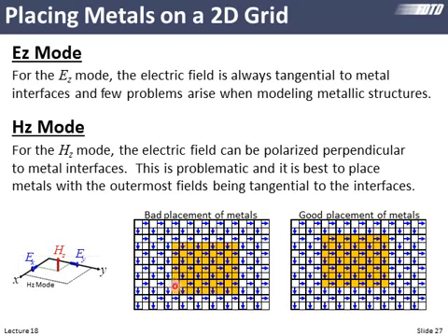If we go down this side, we see the normal component. This is bad. This will converge very, very slowly. We're going to need very, very high grid resolution to get an answer in this arrangement. This is the correct placement.